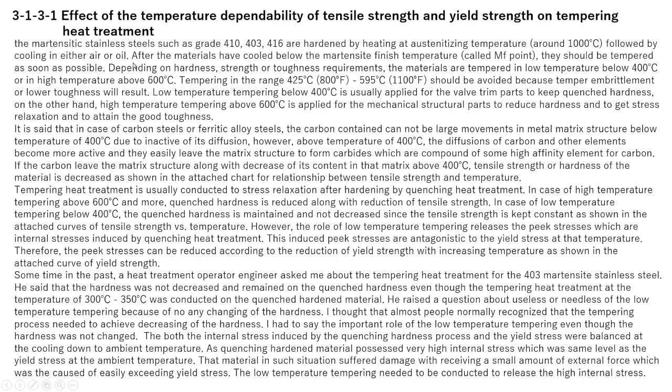After the materials have cooled below the martensite finish temperature, called the Mf point, they should be tempered as soon as possible. Depending on hardness, strength, or toughness requirements, the materials are tempered at low temperature, below 400, or high temperature, above 600 degrees Celsius.